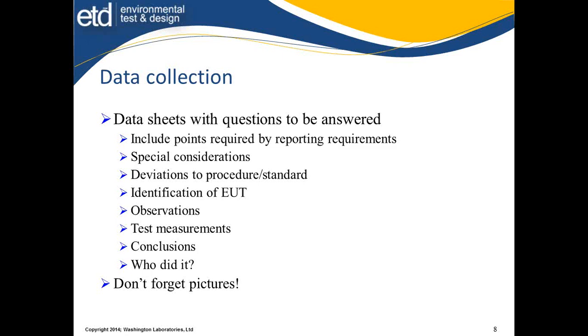You should have a place to record observations, things that may not be showing up as part of the standard, but I realized that there seemed to be a sound coming from it that I couldn't duplicate. Something to record what was going on. There seemed to be an aroma coming from it of something burning, but I couldn't identify anything that was overheating. These observations can point to a potential flaw later.